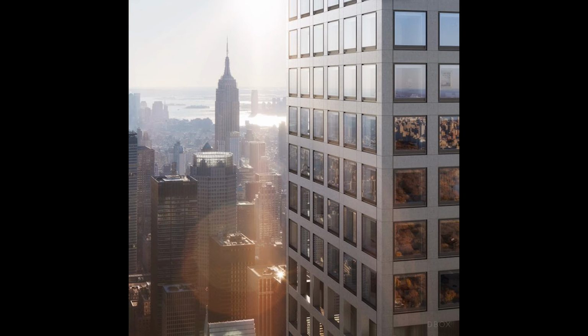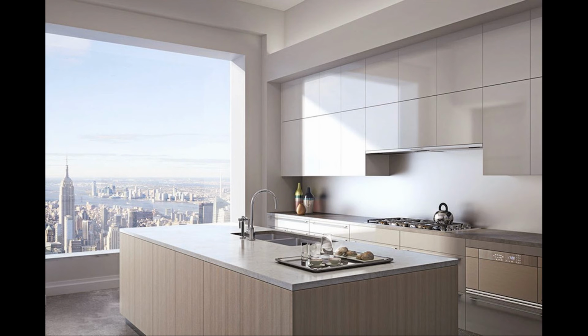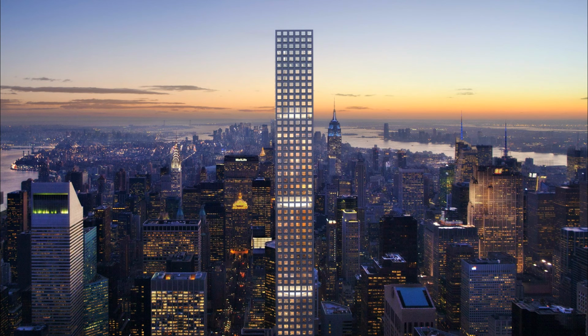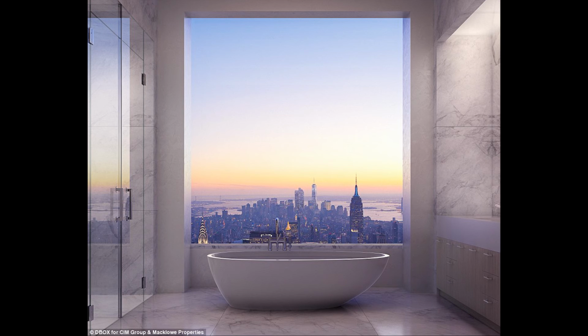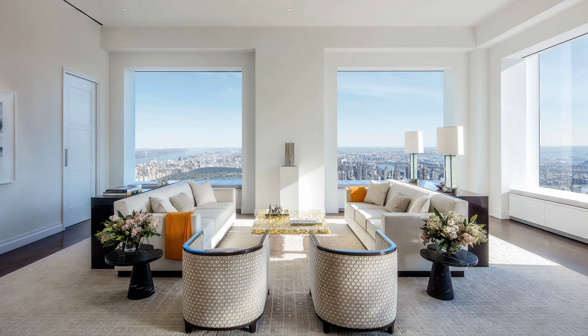Having such large windows on all sides of the tower is likely to create large amounts of heat loss in the winter and overheating in the summer. The current double glazing could be replaced with a more highly insulated system. All windows sit within the structural frame. This is much deeper than the windows themselves, so the total thickness of the windows could have been increased to improve the thermal performance of the glazing.